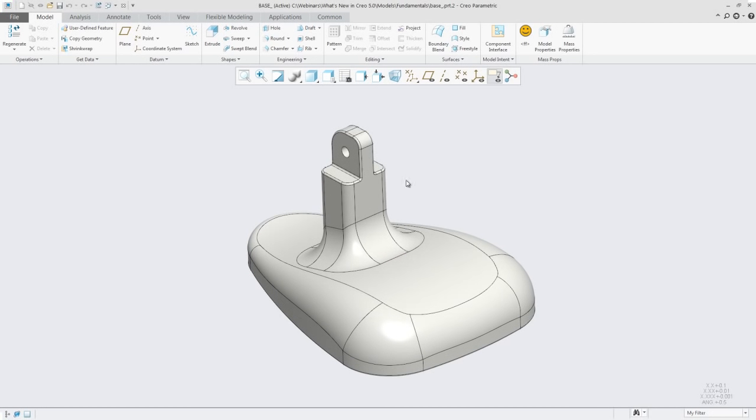Now, as we see, obviously it's loaded in this orthographic view, obviously the default setting. So in Creo 5, we can now model whilst maintaining perspective view, so the system does not default back to orthographic. For those of you who noticed in Creo 4, the render tab has been removed. This is normally where you would have found the perspective view icon.